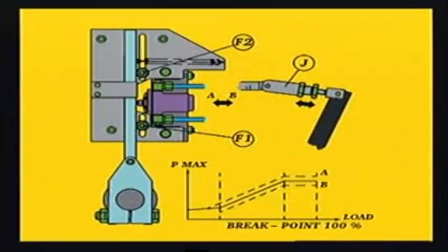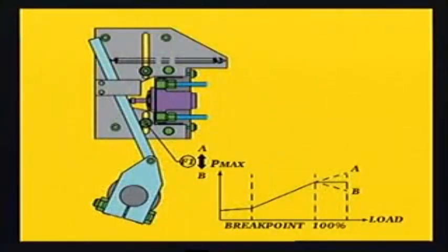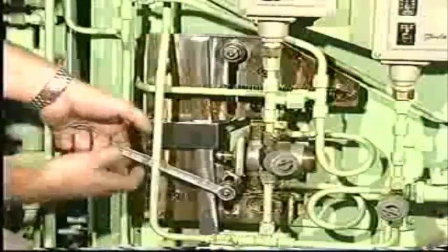Adjust the links until all maximum combustion pressures are uniform, and then displace the pilot valve bracket until the average combustion pressure, corrected to ISO ambient conditions, is at the required value. Load the engine so that it corresponds to 100% MCR load and displace the lowermost pivoting point until the average combustion pressure, corrected to ISO ambient conditions, is at the required value.